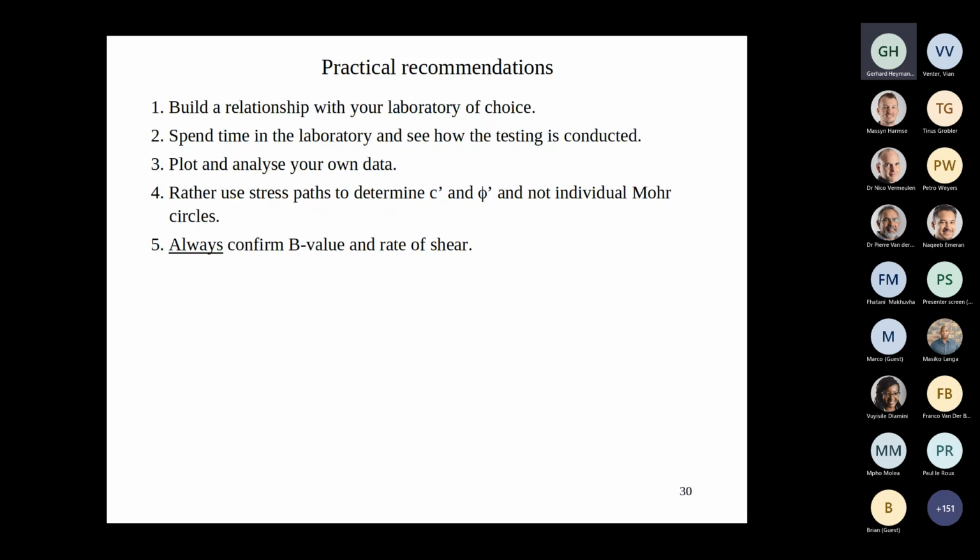Of course, there are stress history effects and so on, so you need to think about it a little bit. Multi-stage consolidation, no problem. You will get extra information with regards to the bulk modulus in terms of the swell characteristics and so forth. I'm a big fan of multi-stage consolidation testing. Multi-stage shear testing, no. I can't get my head around that, and I wouldn't. Look, if you want to save money, save it elsewhere, not on a few triaxial specimens. That's the wrong place to try and save money.